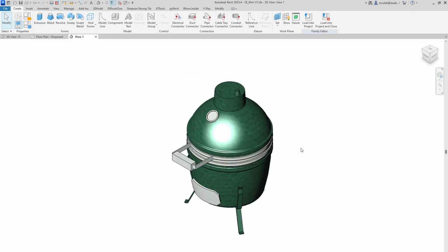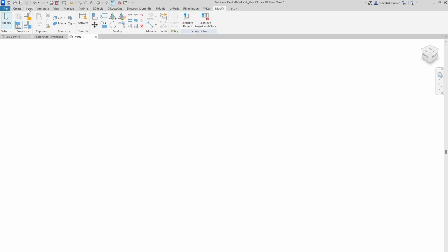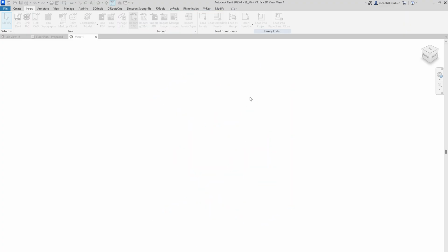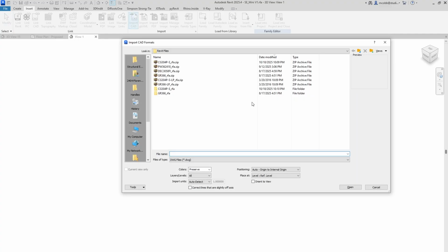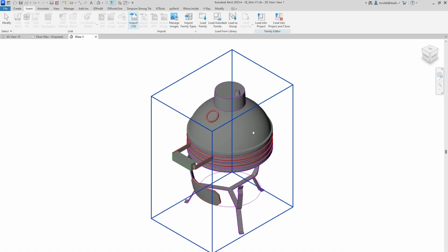and we look at this as I bring it in, I'm going to delete it for a second. I had several attempts at this before it actually started working. So if I insert a DWG, which is the shuttle file that I use to go from Rhino to Revit pretty consistently, and I do this, you can see I've got several attempts here before it actually worked. And if I take, say, this one here, where I was still using those fillets, and I bring it in, you can see I get this emptiness here.